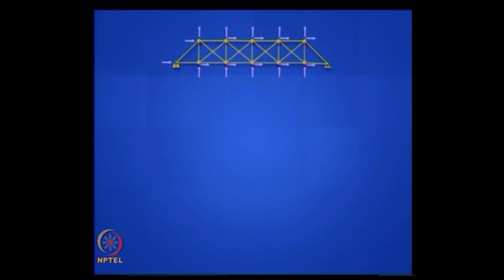So this really means if these are your active degrees of freedom, number them 1, you got 1 here, 2, 3, then don't go along the longer direction, go along the shorter direction, 4, 5, then you can either go here or here, 6, 7, 8, 9 and so on. Does it make sense?